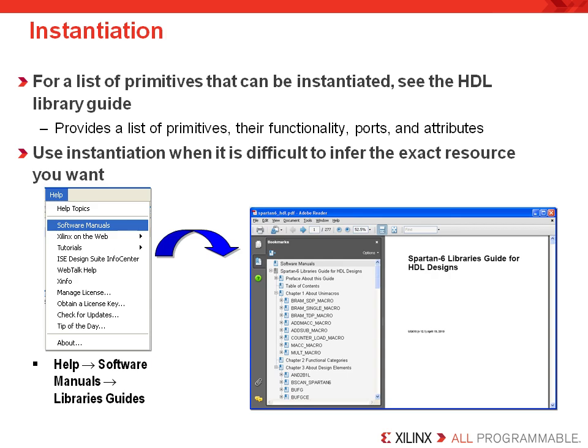As I mentioned earlier, a list of Xilinx primitives and their behavior can be found from the Xilinx Unified Libraries Guide. This is available at support.xilinx.com or can be found from the Help menu in the ISE software. This will describe all the ports and attributes that can be customized. There is also a complete description of the XST attributes located from the software manual webpage. This is always a useful resource for inferring logic and learning good HDL coding styles.